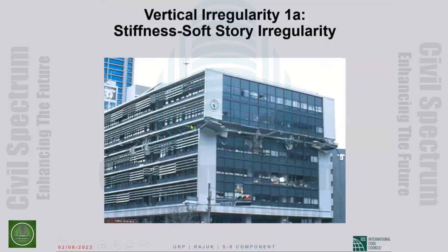And this was the first level with just reinforced concrete shear walls. So there was stiffness discontinuity at that level. There was higher stiffness below and lower stiffness above. The definition says less than story above, but it can be both ways. Anyway, you can see that there is a stiffness discontinuity, and the building failed right there, that level. The remainder of the building was not too bad. The building above was not in too bad a shape, but that level pancaked.